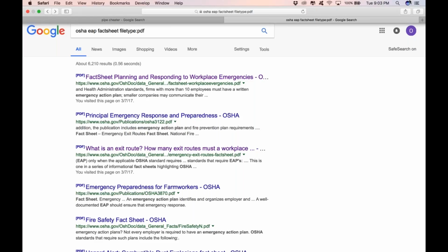During demolition involving combustible materials, charged hose lines supplied by hydrants, fire trucks with pumps or equivalent have to be made available. So we have to have, even during demolition, right, we have to have some type of fire protection and prevention available. Okay. If the facility being constructed includes the installation of an automatic sprinkler system, the installation has to closely follow the construction and be placed in service as soon as practical that laws permit. But in the meantime, folks, we still need fire extinguishers, or we still need some type of pump trucks or something there readily available to put out any fire.